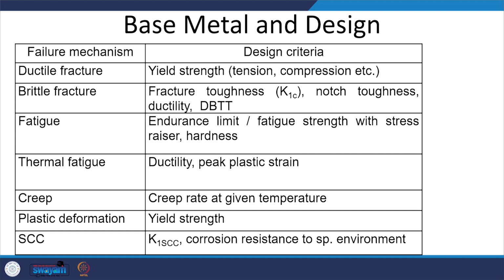Okay. Say, let us understand this in this way. Say, these are the two set of the components. Okay. Edge has been prepared. So, in case of the thick sections, edges need to be prepared like this. Okay, like this, and this section has to be filled in. So, for filling in, what we are using, that is the part of design. Okay. This is applicable especially in case of the consumable welding processes, where suitable electrode or filler metal is used.